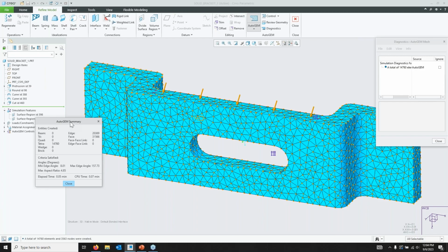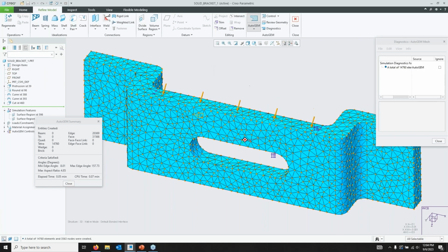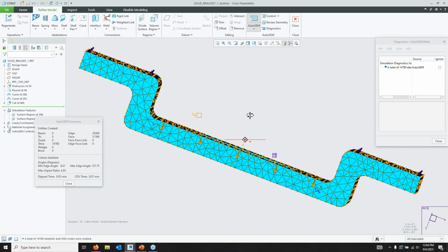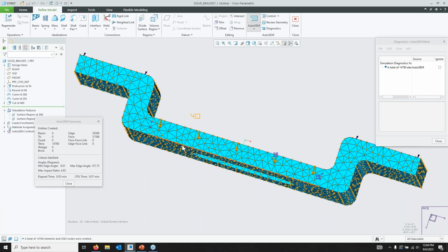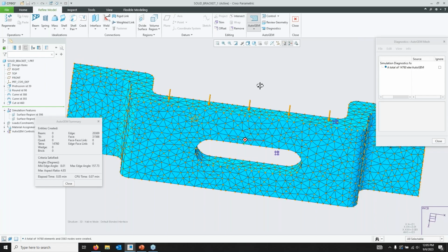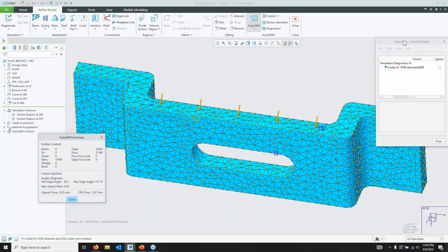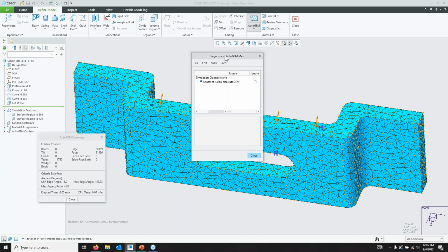So simulation really, at least in terms of optimizing the mesh, it's more of an art than a science. I like to use, at least as an initial goal, getting 3 elements across for any part of our model. But how accurate your mesh gets, how fine your mesh gets, is really going to depend more than anything on your computational power and how long it takes you to run these simulations. The art to it is getting your results as accurate as you can without making your simulation take weeks of your time.